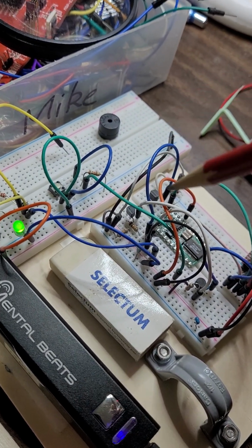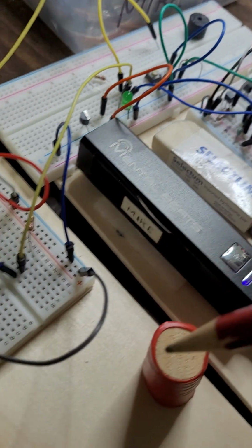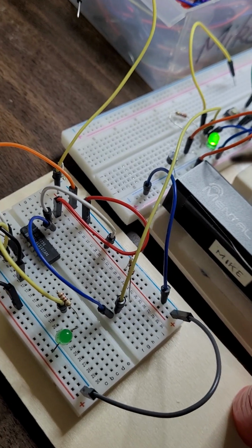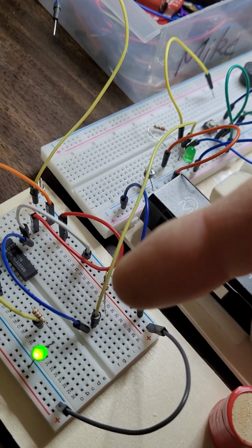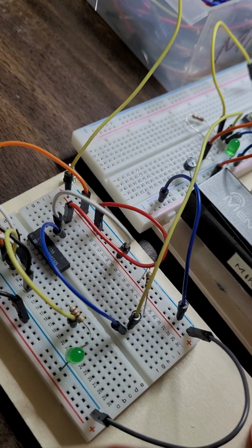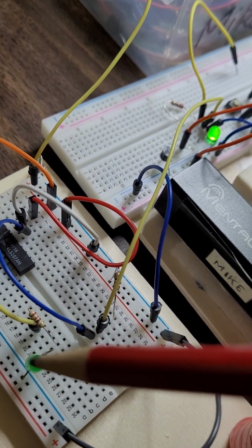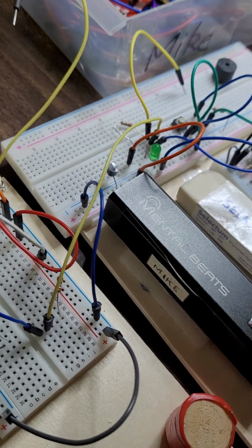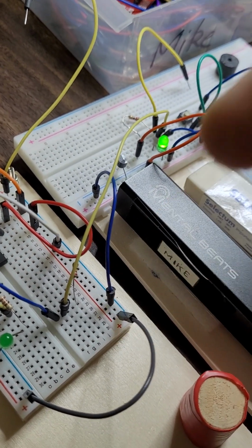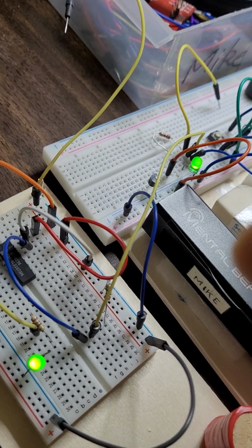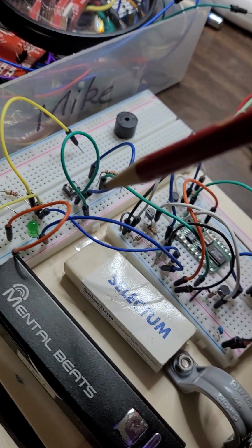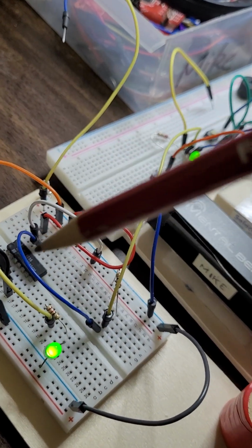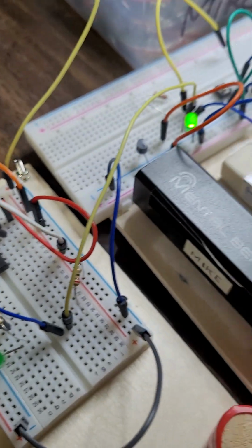Of course, if instead of using this as a source to demonstrate the JK flip-flop you use a switch and press it with your finger, because of jitter, the switches and your fingers will deliver a lot of noise, and this will turn on and off hundreds of times without your eyes even noticing it. That's why it's really not good to use a mechanical switch for this demonstration, because of the noisy mechanical switches. You have to use digital electronics to get a clean square wave output from the JK flip-flop.